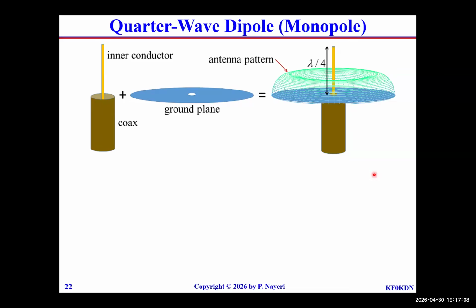And in the case of the monopole, it's going to look similar to that one. But as the antenna becomes shorter and shorter, the current looks like this, and eventually the current is going to be really small. So you don't have much of a time varying current, and you have a huge mismatch problem. So electrically small antennas are a challenge to design. There's a limit known as the Chu limit that dictates it, but generally speaking, their efficiency is low.